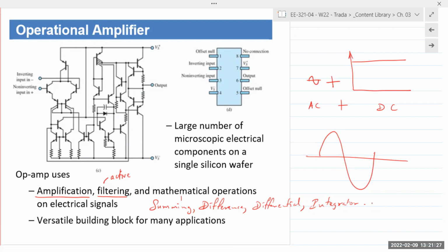If you analyze that same circuit in the time domain, you can say it works as an integrator because it integrates the input and gives it to the output. If you analyze mathematically in the frequency domain, meaning you're only considering the frequency of the input, then you can say it functions as a low pass filter. Okay, it's the same circuit, it's doing the same two things at the same time. It depends on what you're interested in, right?